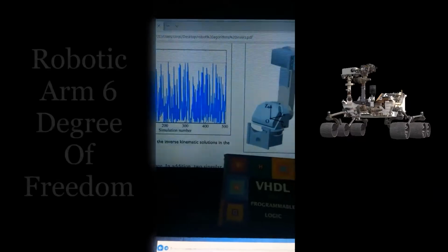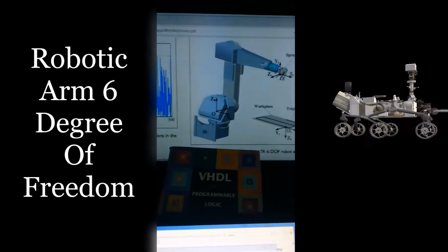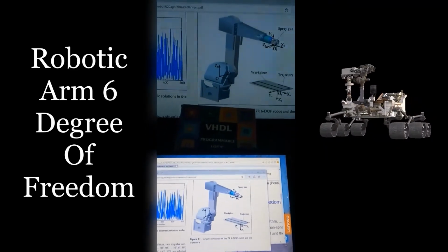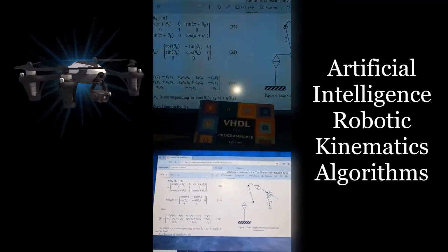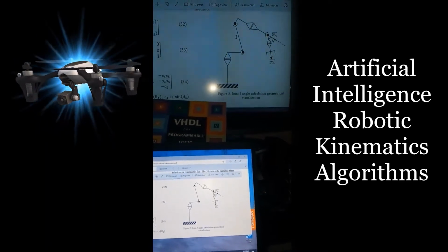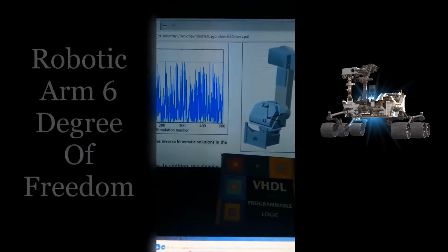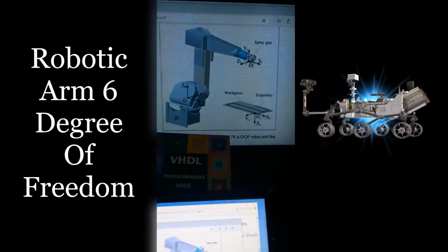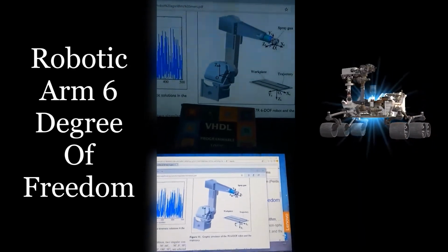Angles of the robot by having the position and orientation of the end effector. The inverse kinematics of a serial manipulator is more important than the forward kinematics, as it is essential to move the gripper of the robot to a required position with a defined orientation to grab an object in that position and orientation.